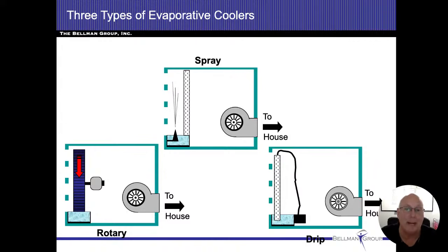And the same rules of science still apply. If I'm going from a liquid to a gas, I have to absorb BTUs. So as I blow moisture into a room and something gets wet, then that moisture, as it changes to a gas, is going to absorb the heat of the items that it's touching. Those items will be cool, and then the rest of the house is actually going to be cool.